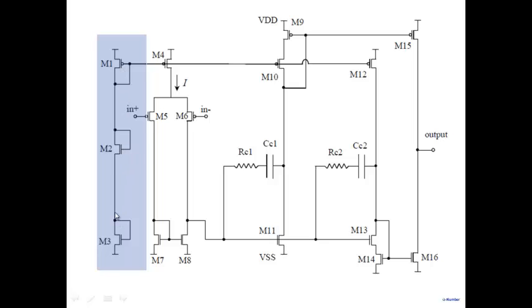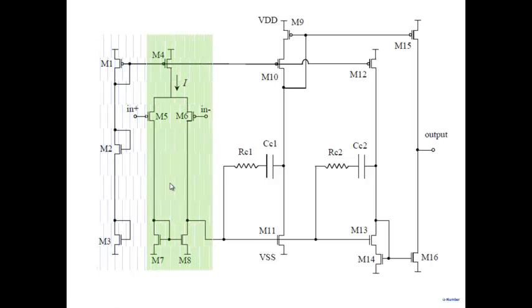So this you recognize as a current source here. What about this one? Let's focus on this one. It's a p-type differential pair with n-type current mirror load, right? And I require biasing some current here, so that is being derived from here. So that's fine. That's a normal differential pair here.